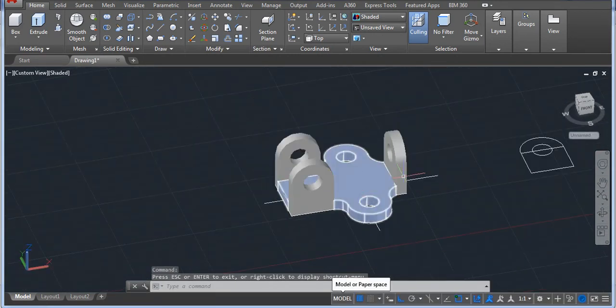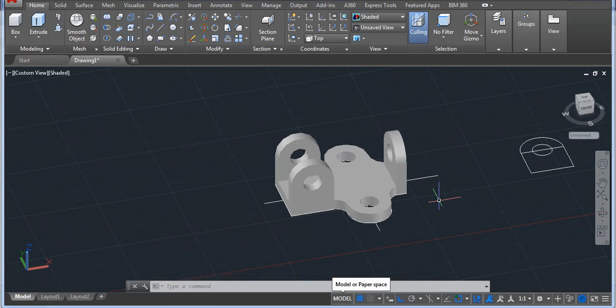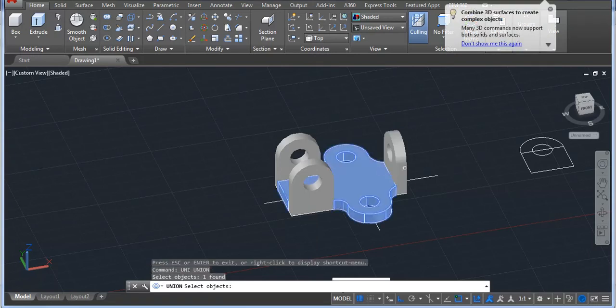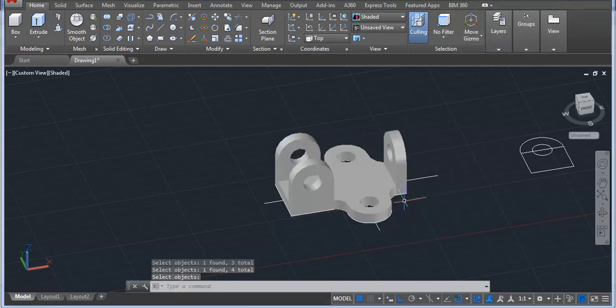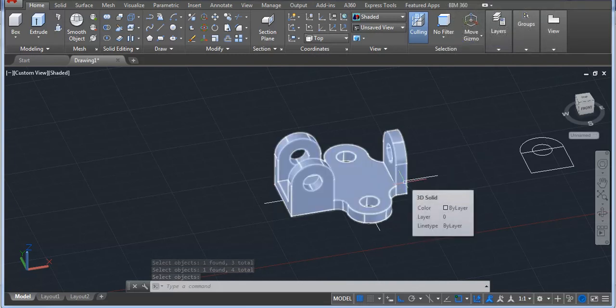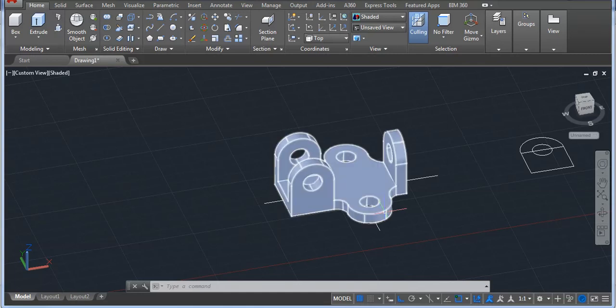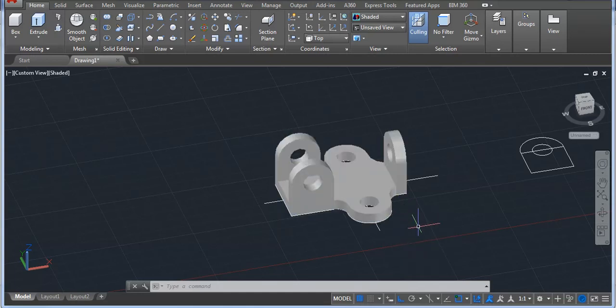You can see first, second, third. If you are okay and very confident that yes, all of these are okay, now you can union. Okay, before the final, don't use the union command. At the end you have to use it, because if you use the union, then you can't break it easily. You can break it, but there are so many issues. So be sure you are done with your working first and then you can start. So that is a custom view.